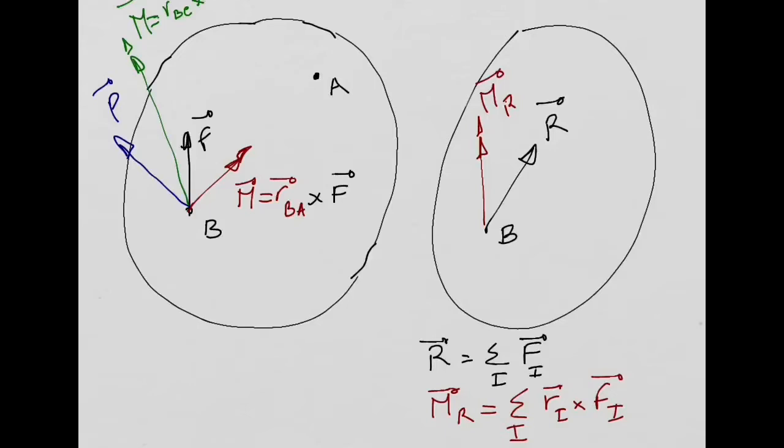And then I will have this equivalent system on the right hand side. This equivalent system here. And then you can see we have everything, forces and moments, concentrated in one single point of our structure. And what are we going to do now to study the equilibrium? Well, I'm going to say the resultant of the forces needs to be equal to 0 to be in equilibrium.